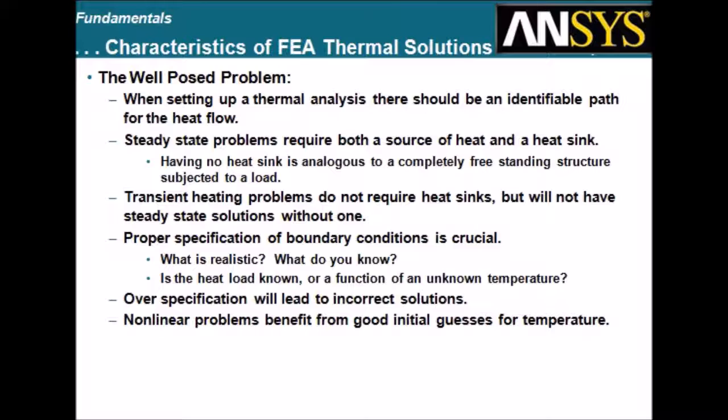Proper specification of boundary conditions is crucial. What is realistic? What do you know? Is the heat load known, or a function of an unknown temperature? Overspecification will lead to incorrect solutions. Nonlinear problems benefit from good initial guesses for temperature.